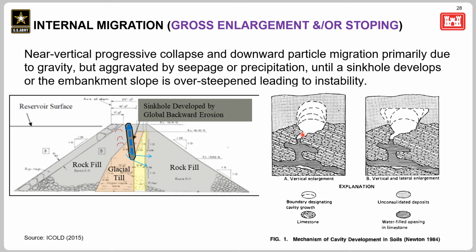This mode may also occur in dikes or small dams constructed only of silty sand and gravel, if there's a potential for particles to be removed from the downstream slope by gravity, under the seepage gradient at a seepage exit where the phreatic surface emerges on the downstream face or toe. The failure mode in that case may look like sloughing or raveling of the downstream slope rather than formation of an opening through the embankment or a big sinkhole.